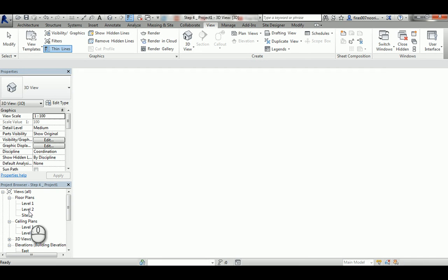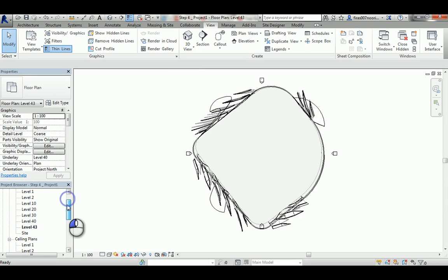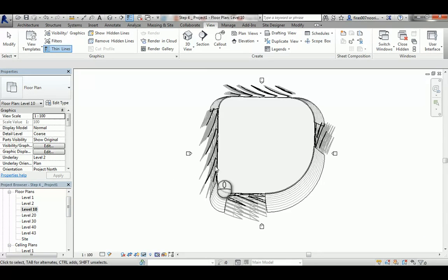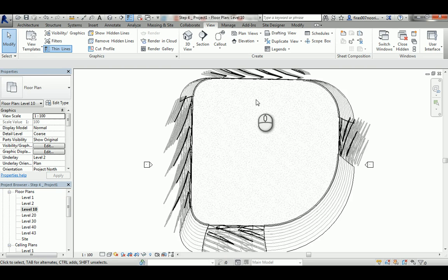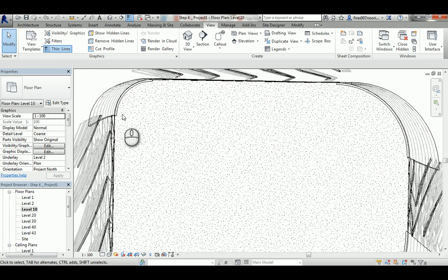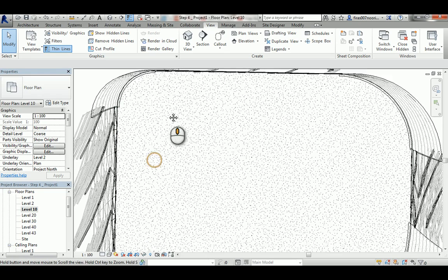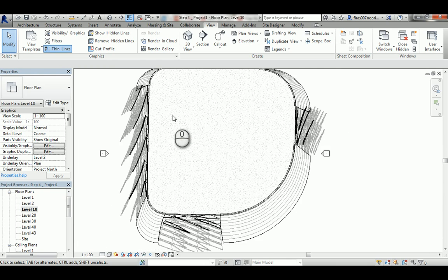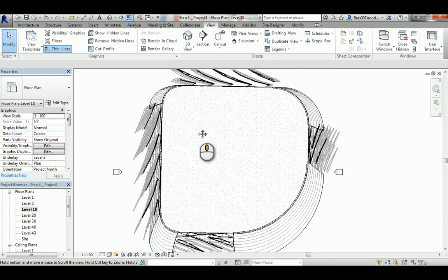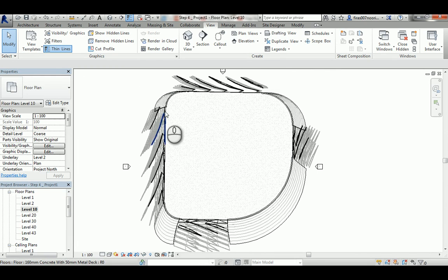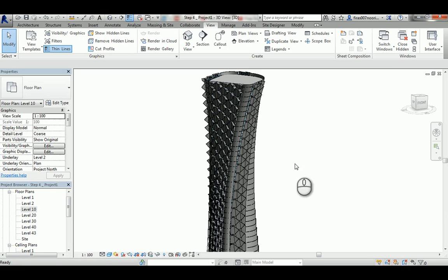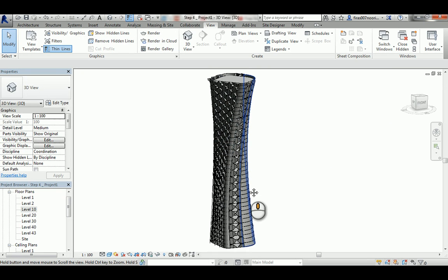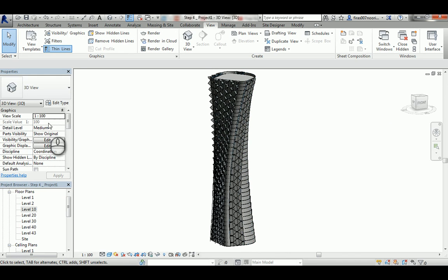So now we're going to generate floors for each one of those, and you can see that it's pretty awesome. That's Revit creating everything for you. It's cutting, and that's the glazing, and that's the actual wall, and that's what happened beneath that level, and so on and so on. So that's the powerful thing we can really depend on when we design such a thing: you don't need to cut each level. Revit will do that for you and create the floors and the views for that. Anyway, that's been done. So that's our tower.